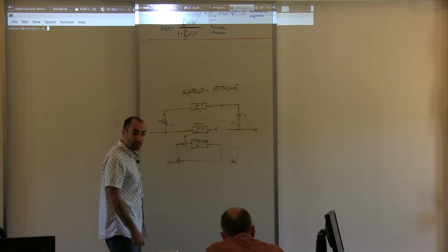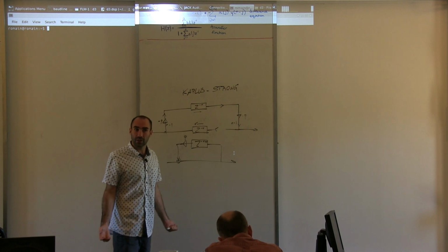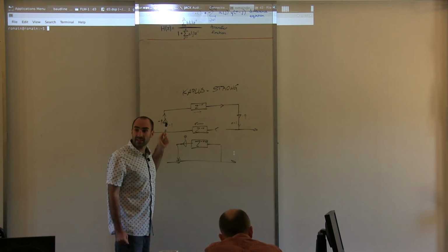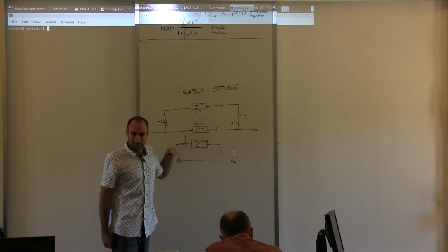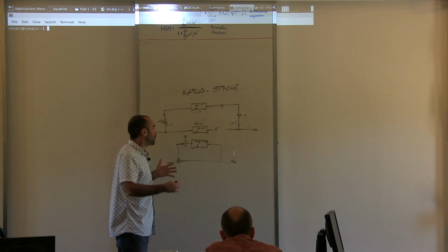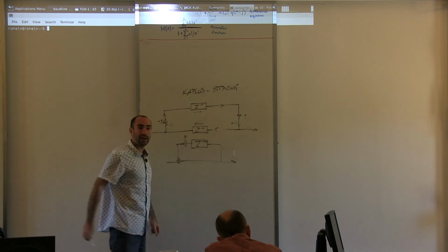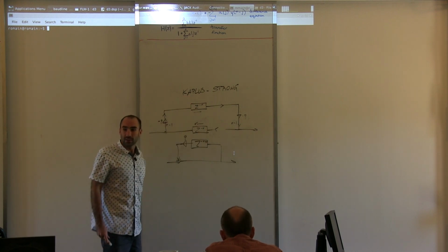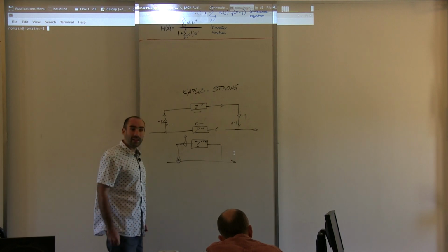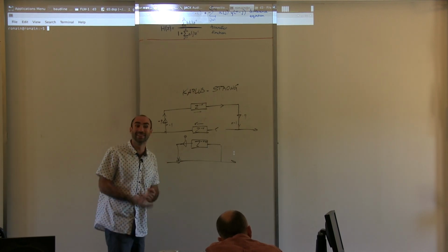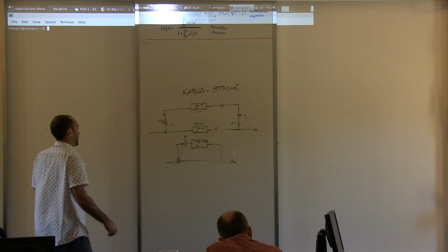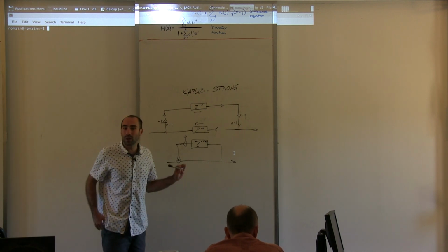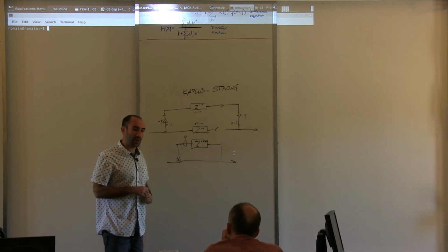Right? And that's a string, and the result is going to be the same as in here, so it's going to sound the same, except that now we saved, well, we didn't save much. The only thing we saved is complexity, just by looking at the algorithm, and we also saved one multiply. We didn't really save memory because the memory that we were using here got translated in here anyway. So we only saved one multiply. But trust me, in the 70s, that multiply mattered. So this thing here is what we call the Karplus-Strong algorithm, or it's almost the Karplus-Strong algorithm, because it's actually missing one little thing to become a real Karplus-Strong algorithm.